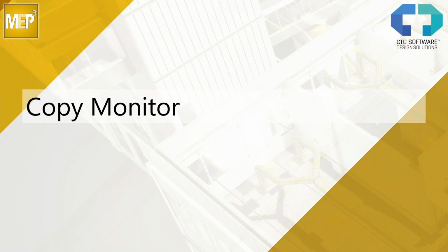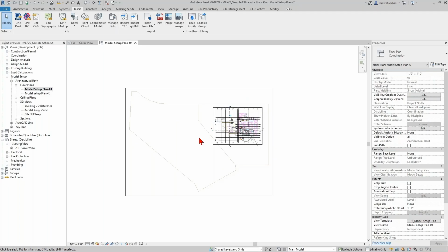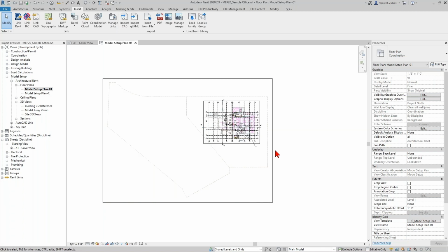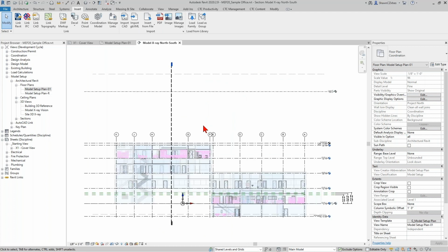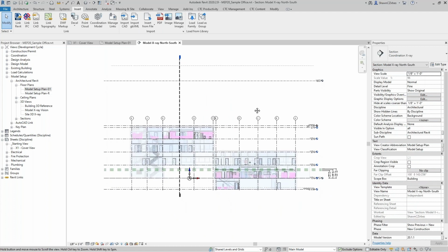And then we're going to get into the meat of the really interesting part of what I think is going on here today. So within here, I'm going to go to either of these 2 building sections. Your choice. Doesn't matter which one. You just go to one of them. I personally like the one that's kind of east-west cutting, looking towards the north side of my building. So I'm going to go ahead and just double click on that and open up this part of my building. And I want to show you a little bit of what's going on with the levels in this template.